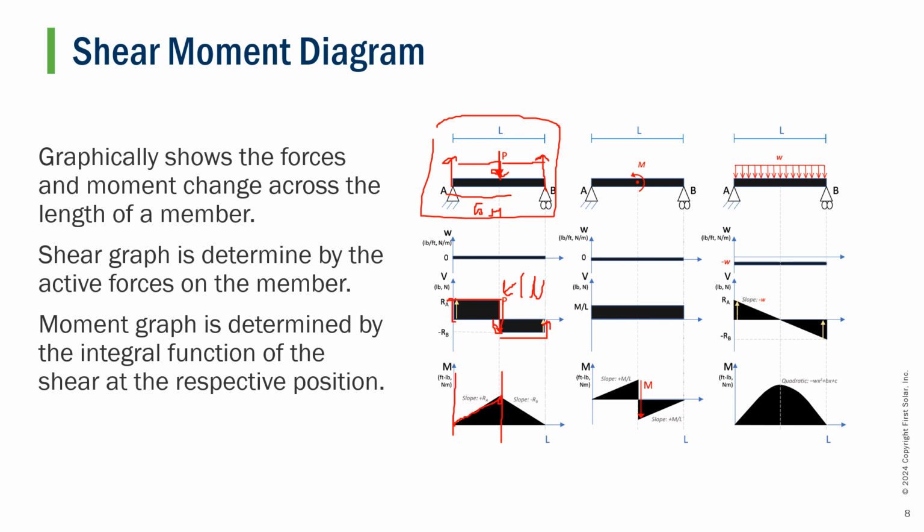Again, we take the integral of whatever this value may be, and we will take this point from the end of the beam to the center, again whatever values they may be, and we will see that we will get a decrease in moment down to 0, where our forces will all equal out and our beam will be in equilibrium.